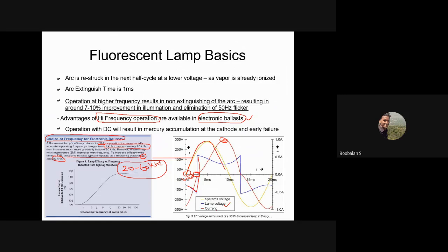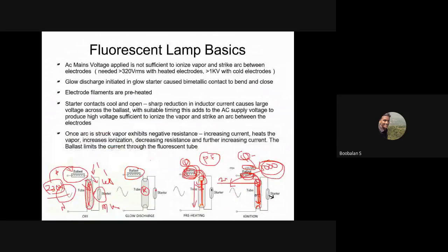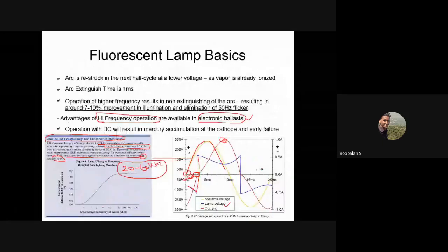Right now, in my magnetic ballast only the power factor is going to be affected. We are just using an inductive type of load over here. That's why my power factor alone is changed, and due to that, the quality of power is also affected. In the fluorescent lamp, instead of the copper ballast, we are using an electronic ballast.